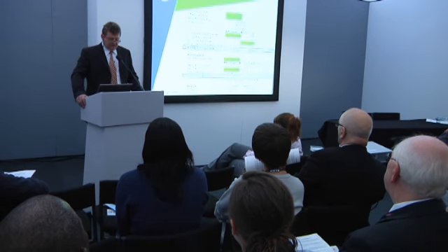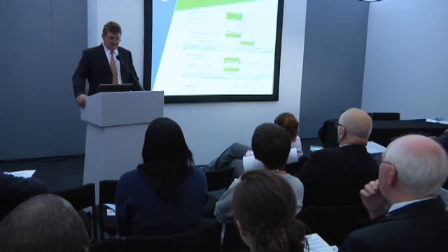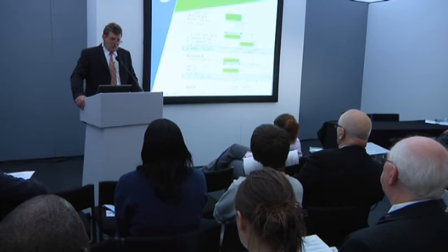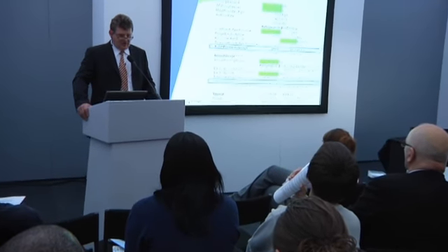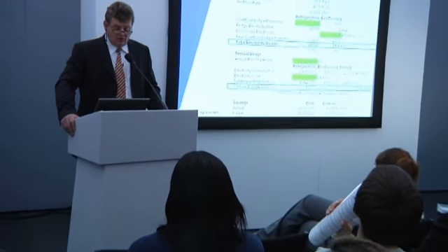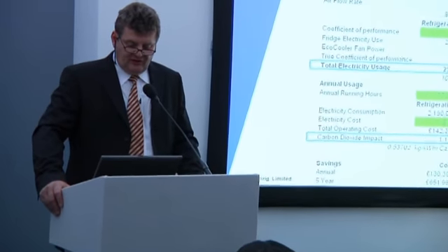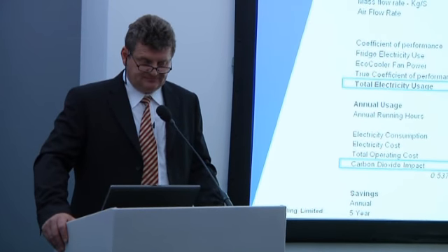That means for the 500 kilowatts of IT load, we will be putting 250 kilowatts of energy continuously into the cooling system. The equivalent capacity of cooling delivered by an eco-cooling CREC system would only require 21 kilowatts of electricity. So you'd see 92% less energy put into that system.